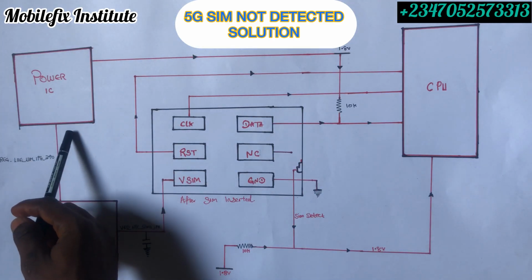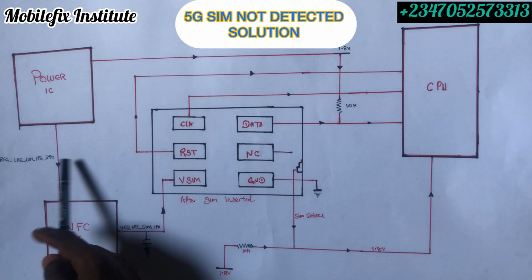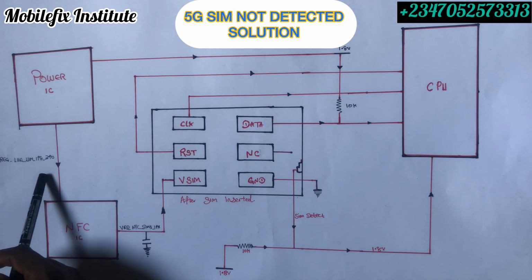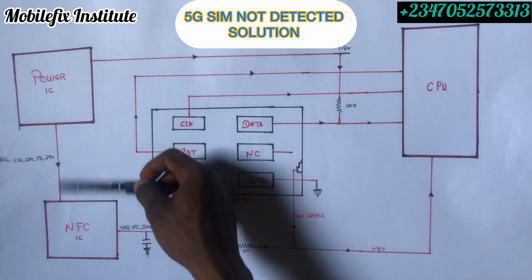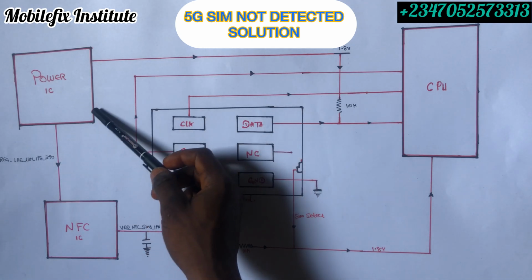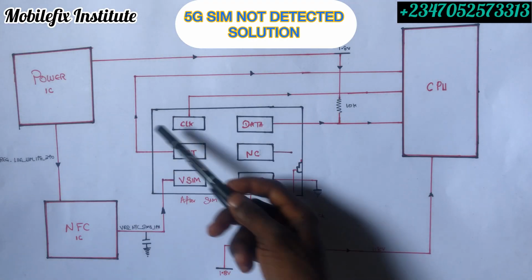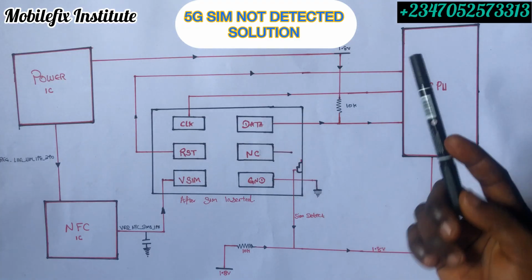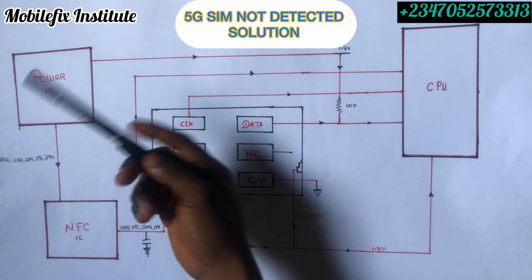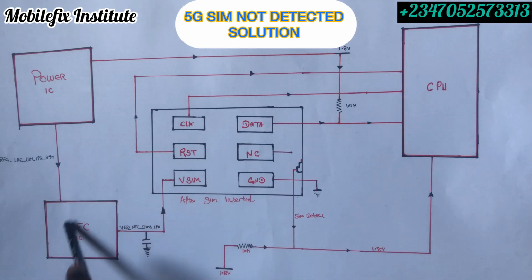Our power IC will give out a voltage. It can be 1.8 volts, it can be 3.0 volts, depending on the circuit or the model of the phone, the one that the company decides to use. They can use 3 volts, they can use 1.8 volts, and this line is our VREC, and we know that our VREC is our LDO line. So now our power IC will generate our LDO line and send 1.8 or 3.0 volts to our NFC IC.